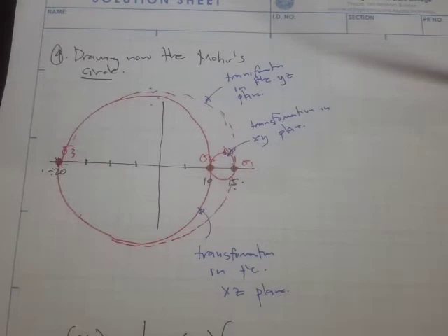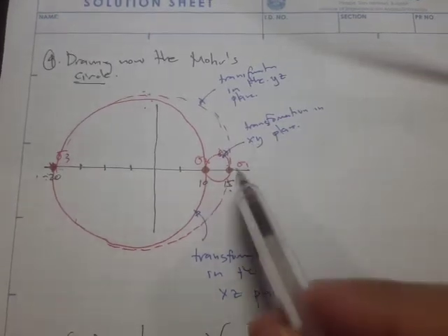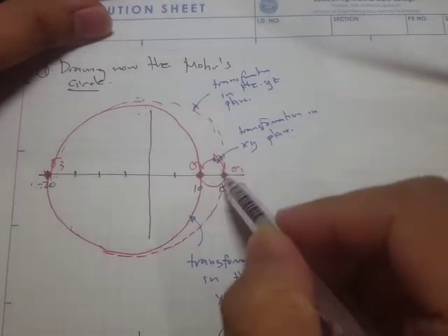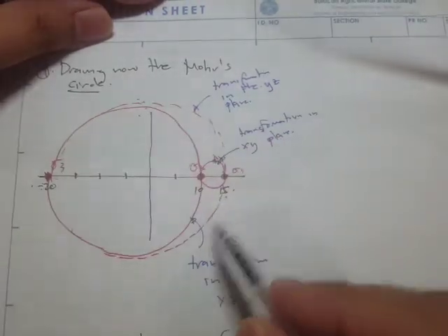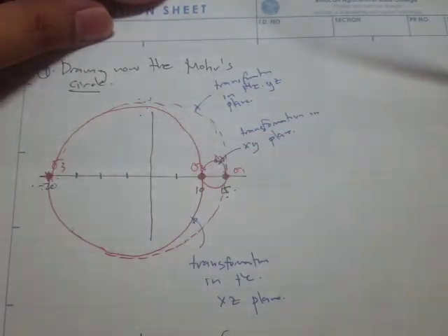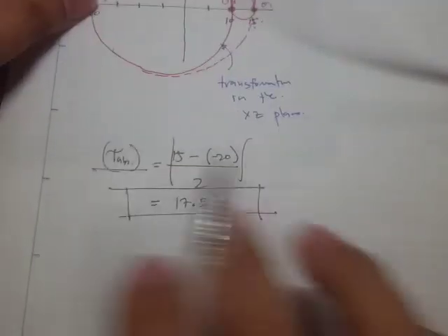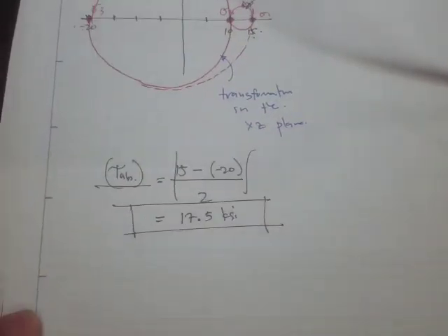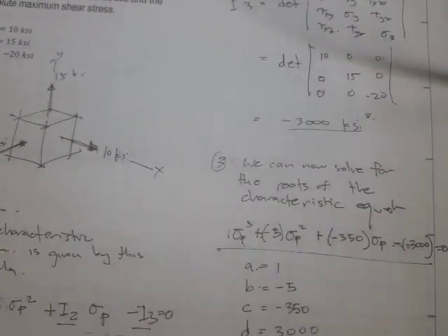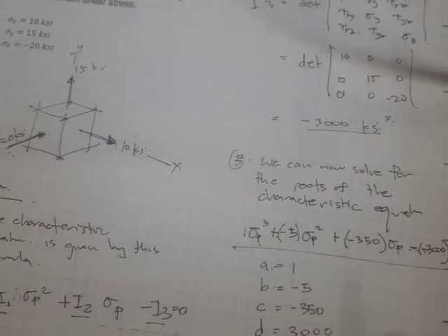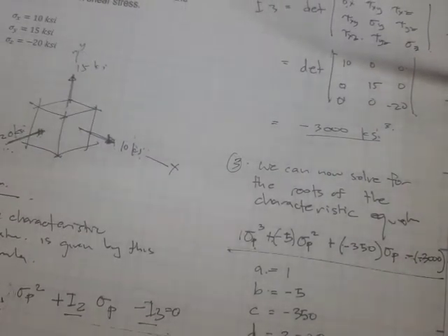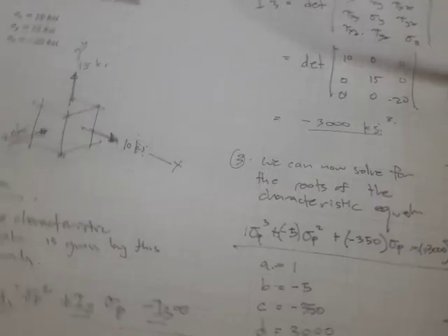After that we can draw the Mohr circle. Since we have three principal stresses, we know that we have three circles right here, and the maximum shear occurs at the radius of the maximum circle. Okay, so that's it. I guess that's all for this stress transformation topic, but we still have time to do one more sample problem about the application.